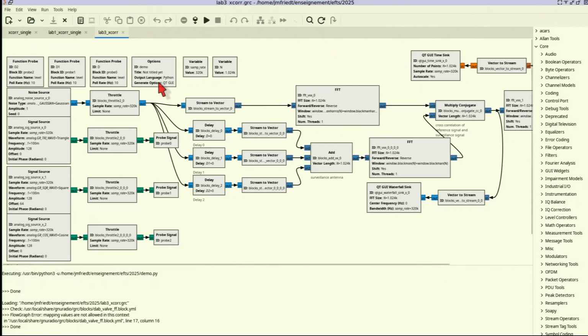How do I demonstrate this? Exactly the same story as before. I have a noise source. The noise source feeds the reference channel. And now I have 3 delays. These 3 delays are varied, this time so that I don't change my delay manually, by a triangle wave, a square wave, or a sine wave. And these 3 delays are defining the delays of the 3 targets.